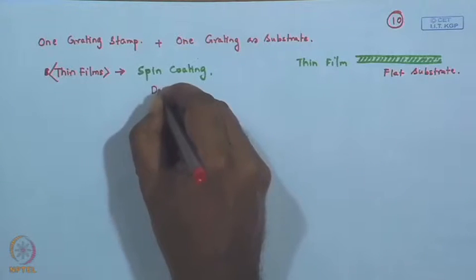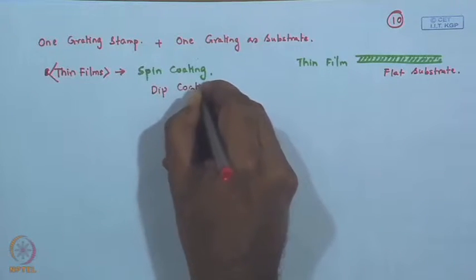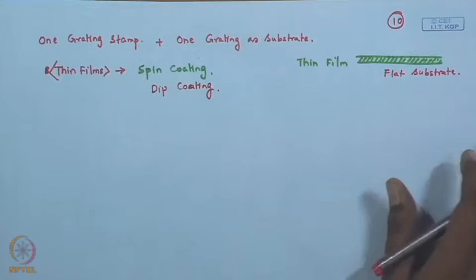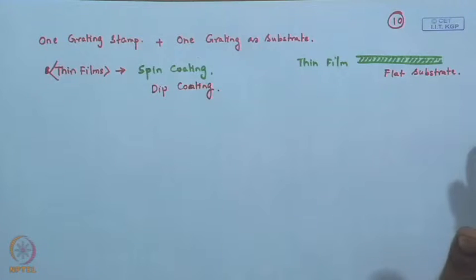For thicker films, spin coating can still be implemented, and industrially it is also implemented, but there is another nice technique that can easily result in few hundred nanometer to few micron thick films, which is known as dip coating. But for the time being, we will keep our discussion limited to spin coating. So, in all this CFL, SAMIM, MIMIC, we have implicitly assumed that we understand spin coating, and the thin films we have been talking about have been spin coated.